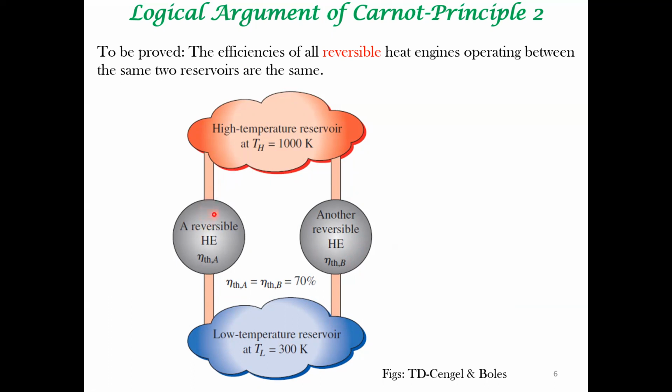I mean, there is a reversible heat engine, and there is another heat engine which has been reversed to become a refrigerator that is delivering QH to the high temperature reservoir. So the amount of heat taken by one heat engine is the same as the amount of heat that is delivered into the high temperature reservoir by the refrigerator. So that part gets out.